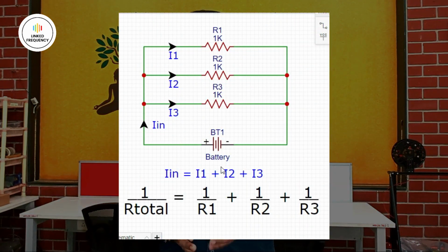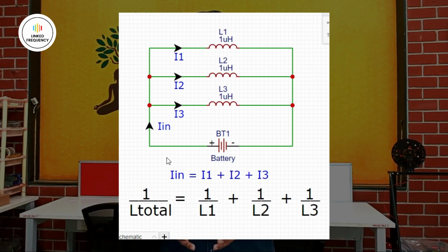The parallel connection means connecting electronic components to the same point and making them parallel to each other. For example, connecting resistors in parallel, capacitors in parallel or inductors in parallel. Contrary to series connection, in a parallel circuit, the voltage applied to each and every component will be the same, but the current will be divided throughout the circuit. In a parallel circuit, if any one component gets damaged, then there is still a possibility that the other components or the remaining circuit may function properly. But due to current distribution, malfunctions can be expected due to failure of any component in the entire circuit.